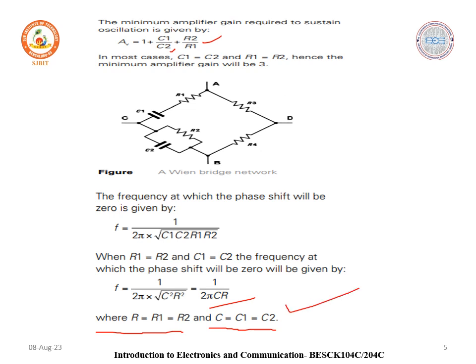So we can use that. We can use different capacitor and different resistance values, but we have to simplify this equation. We are going to consider the common resistance and capacitor value. So you can design the resistor and capacitor values for different frequencies. We can keep the capacitor constant and vary the resistance with respect to that. So instead of varying only one resistor, we proportionally vary the two resistance values, so that we can keep the resistance values the same.